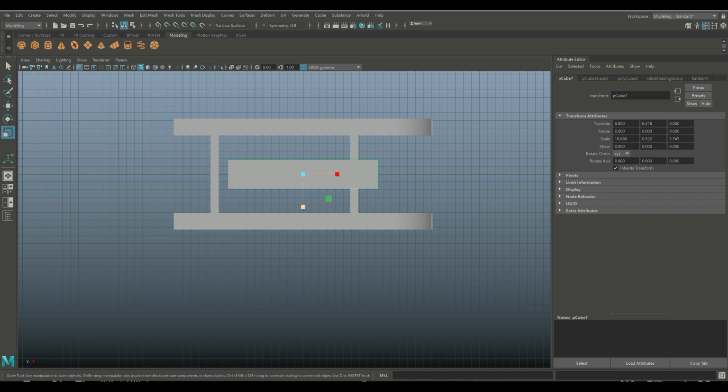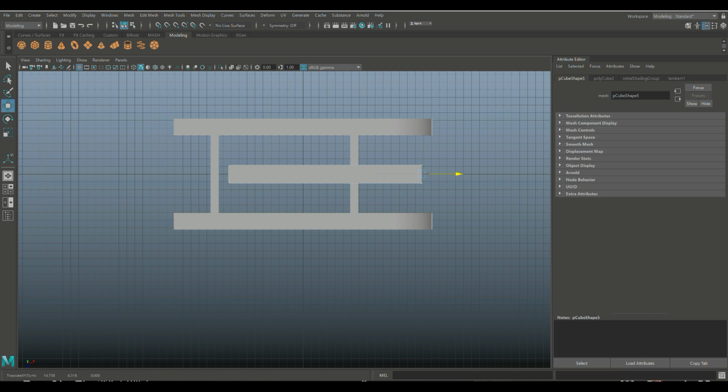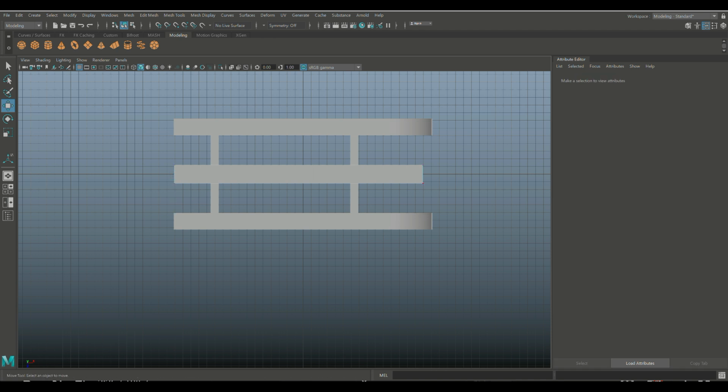So we kind of need to level that out a little bit. So that would be something like this, and then I want them to stick on the front, and that needs to align with what we already have. So I'm going to right click, go to Vertex, drag select, W. That's going to be about here, I would say. Maybe back just a little. I'll explain in a second why, right? And then in the back there, excuse me, in the back, I want that to kind of be modeled in a certain pattern, but we'll deal with that in a second, right? So this should be about right.